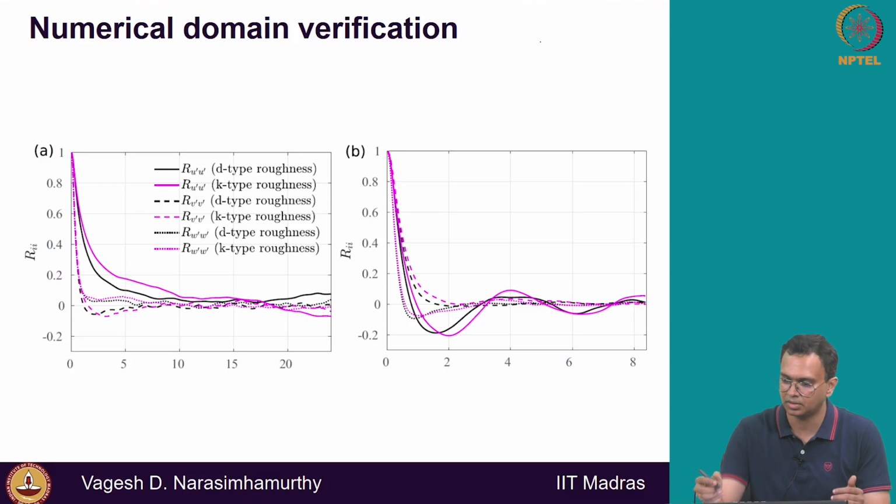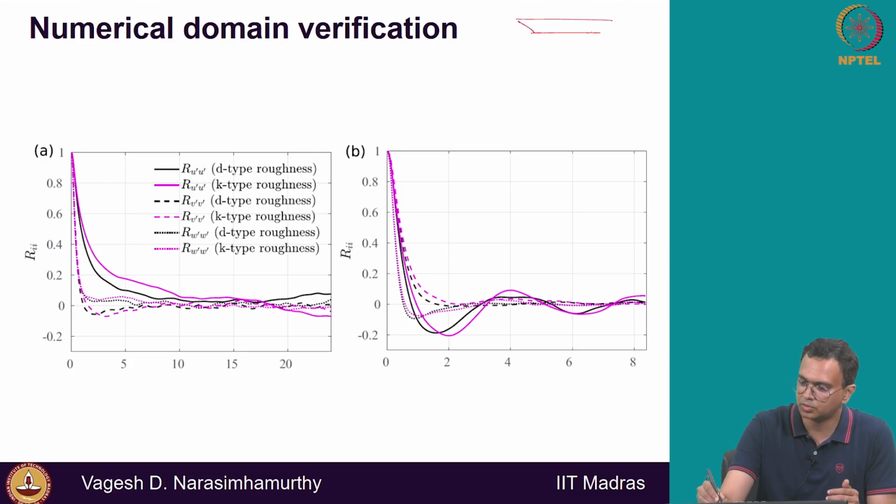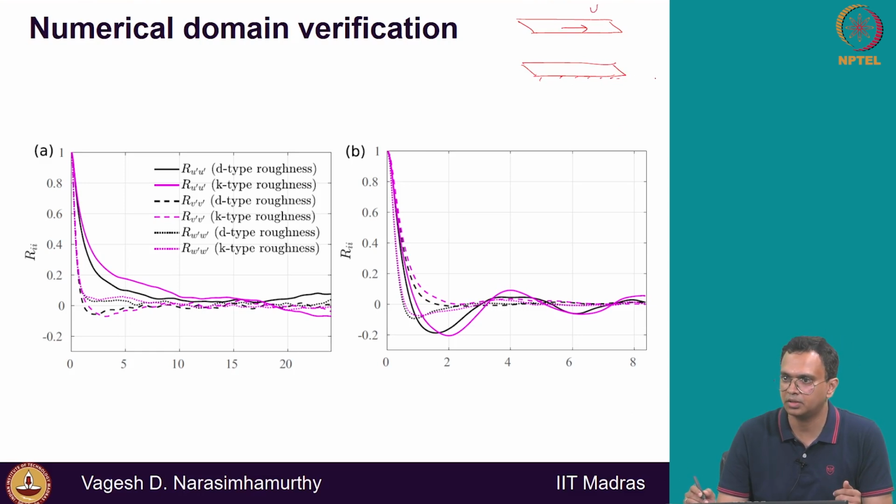It's a plane turbulent Couette flow. So if you have a plate like this, and then I have another plate, and this is moving, this is fixed. That's the definition of a turbulent plane Couette flow. In this problem, we may think that the gap here, let's call it h, is the size of the largest eddy. That is before doing a turbulent flow calculation, but in reality we see that that is not the largest eddy.